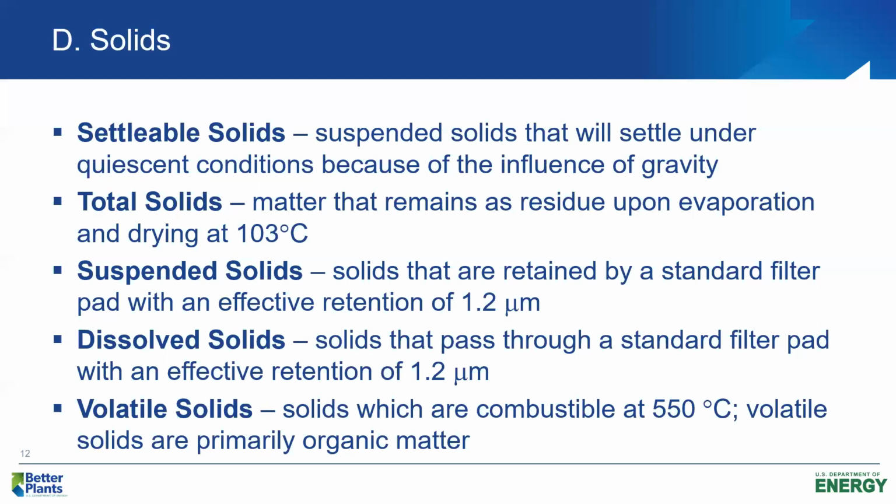So the solids that are retained on the filter, we dry that pad at 103 degrees C and cool it in a desiccator and reweigh it, and then we can actually calculate the suspended solids in the wastewater.